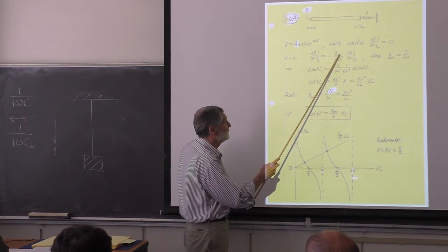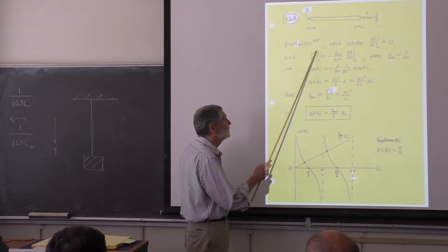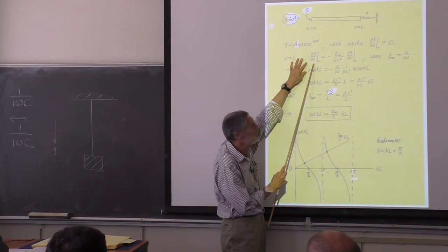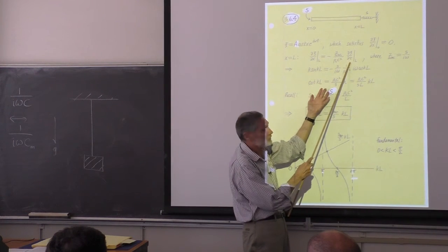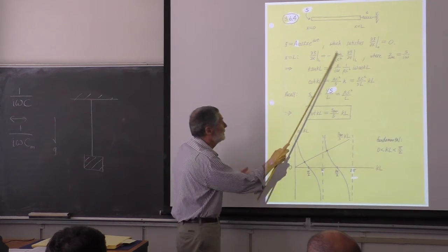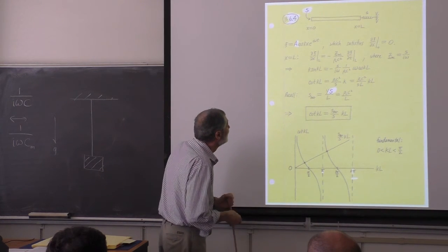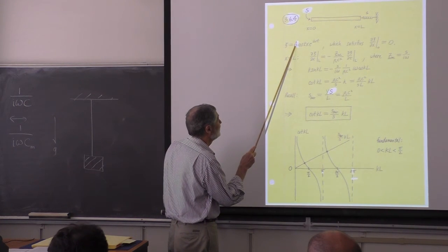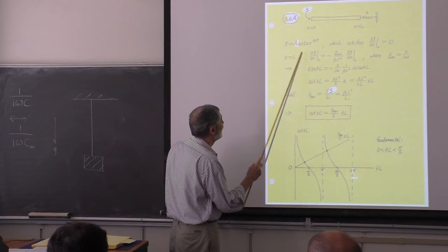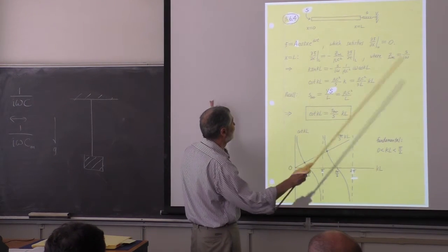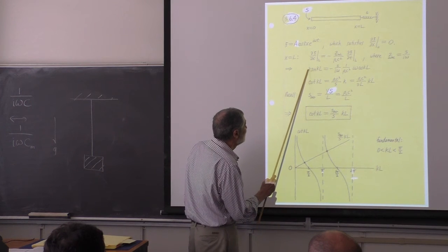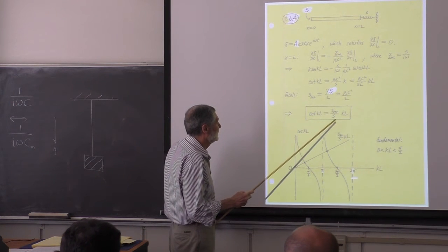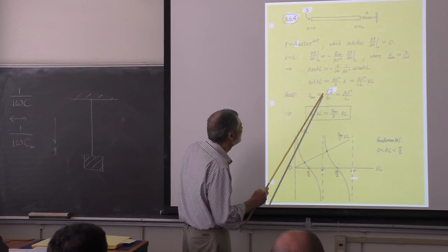This is basically that the terminating impedance is the complex force divided by the complex velocity. You can see this is proportional to the force, the rate of change of strain, remember? And this, of course, is the velocity. So that's what it's equivalent to. So we plug in our form here, and the amplitude is irrelevant. This is all linear, it scales. There's going to be an A there, and it falls out. So we end up with our transcendental equation here. The next step would then be to solve this. And we want to put it in nice form.